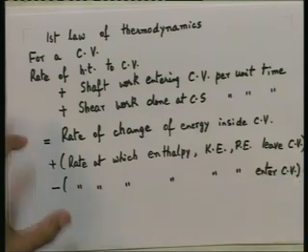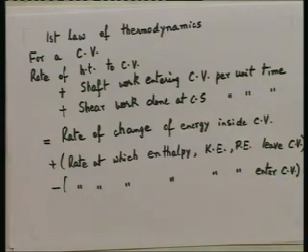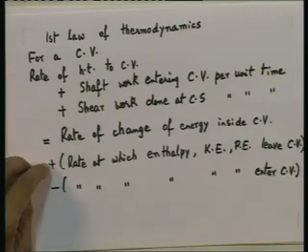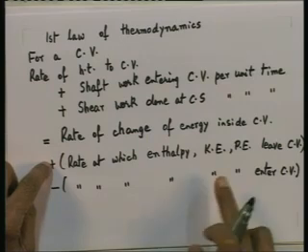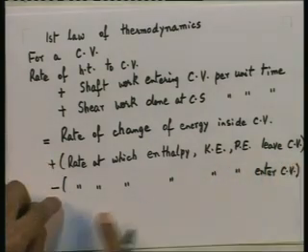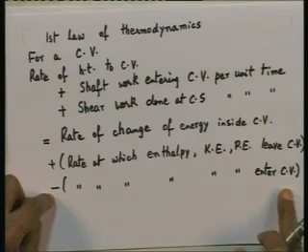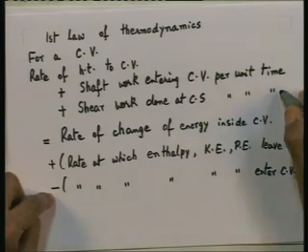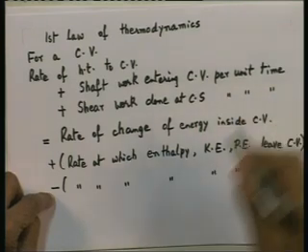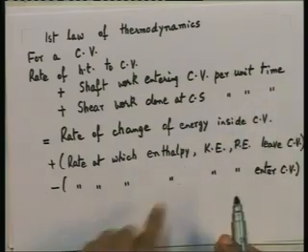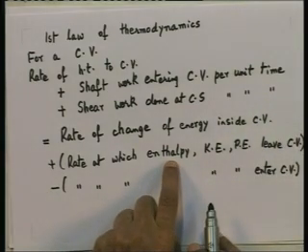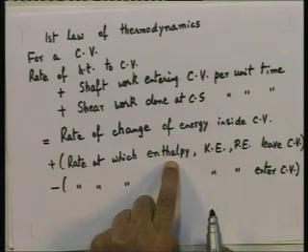All right, this would be the statement in words. Now, notice a few things. The extra terms because of the control volume approach are right here: the rate at which enthalpy, kinetic energy, and potential energy leave, and the rate at which enthalpy, kinetic energy, and potential energy enter the control volume. And instead of writing the pressure work done by the pressure forces out here, we bring that term to this side, and instead of writing internal energy, we write enthalpy. That is really the change that we are putting in.